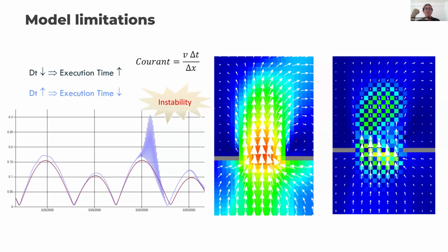And there is one non-dimensional number that controls the stability of the model, the Courant number. The Courant number measures the space, so a velocity times a time is a space, right? Meters per second times seconds, you get meters. So this is the space that a particle of fluid moves in 1 delta t, compared with the size of the cell, okay?